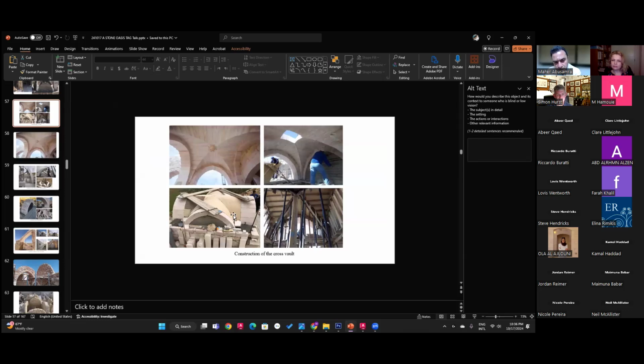Then I started cutting it piece by piece and marking it on site. I put the first piece of stone until touching this intersected profile, mark it, and I have the grinder near me at the top. We are working and cutting it with the edge tilted to make the join between the two pieces. It's hard for the first one, and I will not repeat this kind of detail. After that, when I get another cross vault, I use a normal stone, and when you come to the edge, you can even dress it later on or cut it. Or you can make life easier on your construction when you are trying to build.